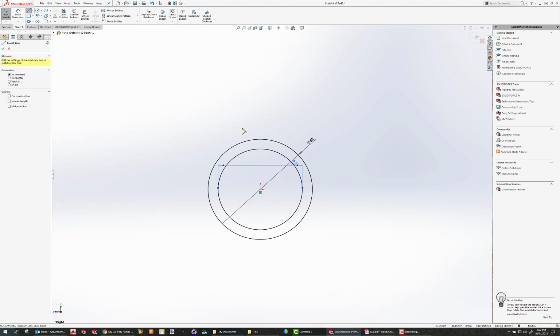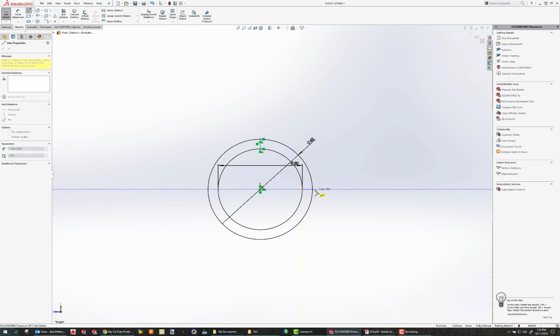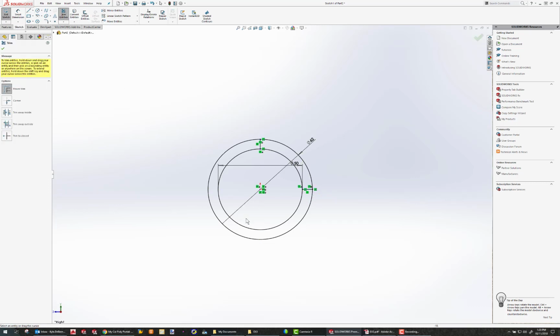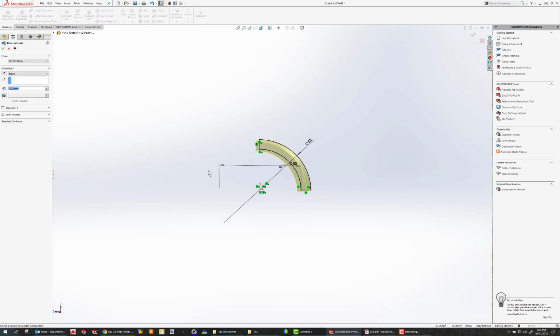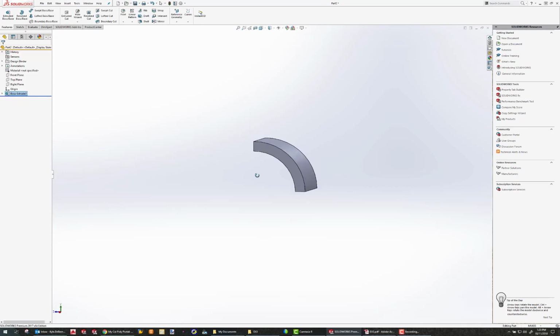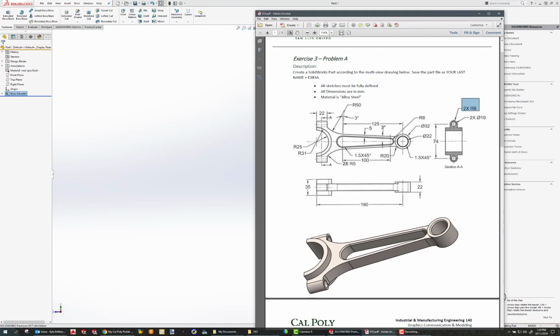And then what I'm going to do is draw a vertical line from there to there, horizontal line from there to there, snapping, and then I'm going to do a little trim. And there I got my first profile that I want to create, and I want to extrude this not blindly but mid-plane, a thickness of 35. So this is my first step. Again, what I just modeled is the top half of this protrusion right there, that's going the thickness, right? So that's the little part that I did.